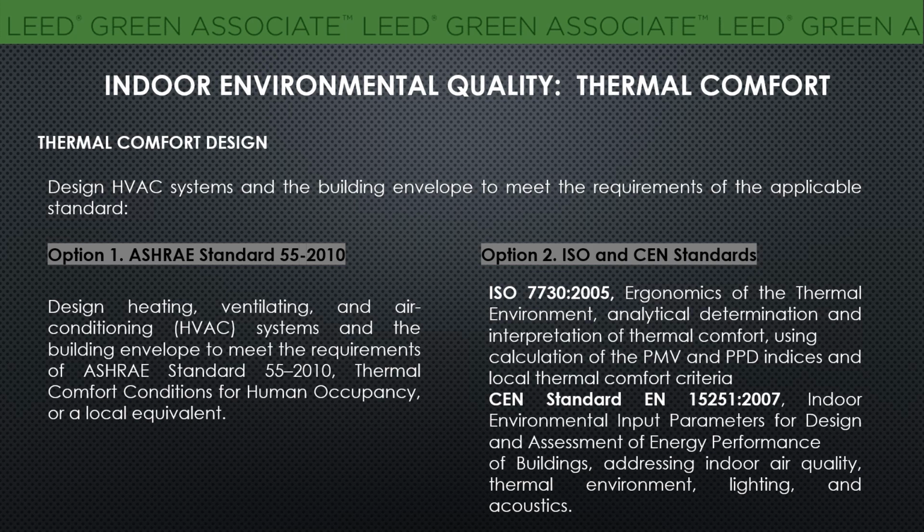Once the PMV is calculated, the PPD is the index that establishes a quantitative prediction of the percentage of thermally dissatisfied occupants. The next code is the CEN standard EN 15251:2007. It is based on the indoor environmental input parameters for design and assessment of energy performance of buildings, addressing air quality, thermal environment, lighting and acoustics. For all these things, we need to follow CEN standard EN 15251:2007. So these are the 3 codes we need to remember.